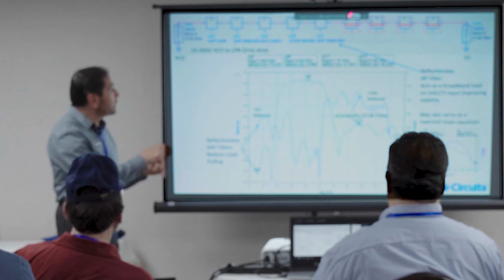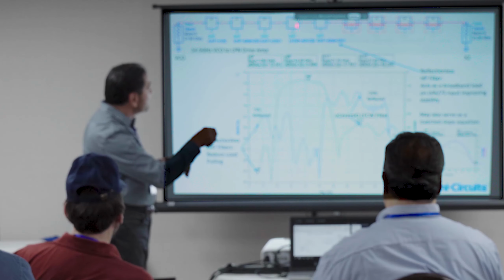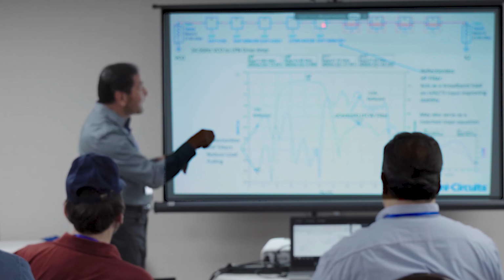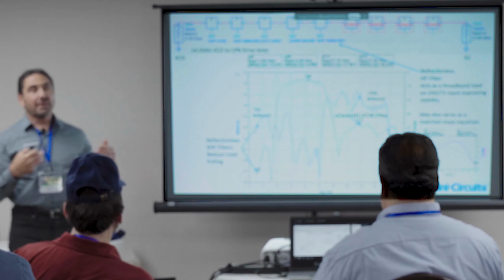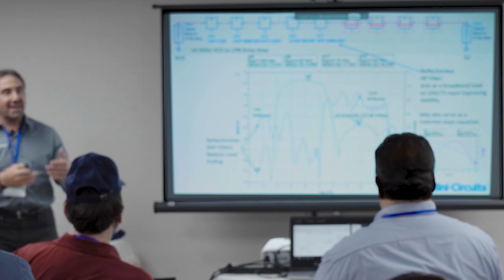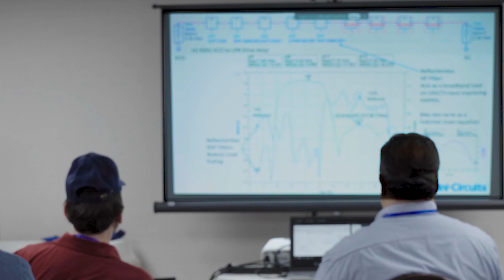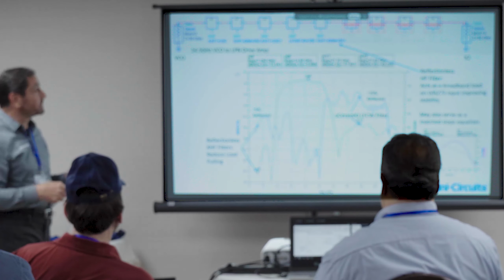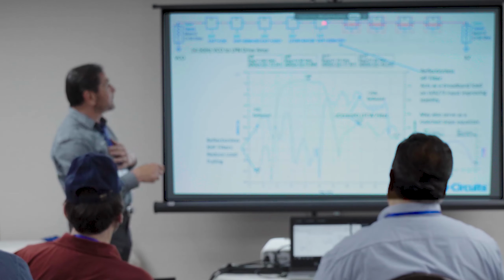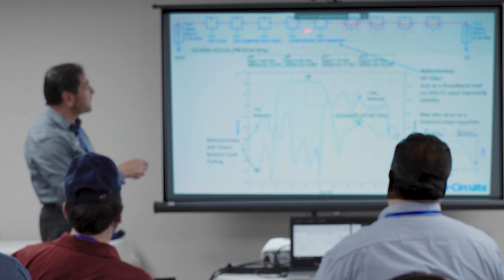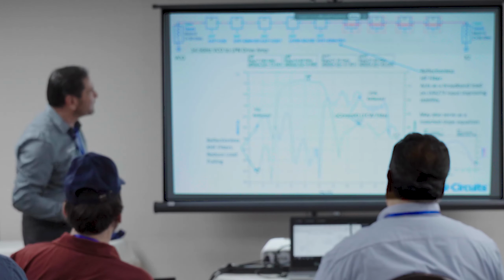When you're working in the reject band of this filter, this is in the pass band, so you get maybe a 2 dB round trip return loss. So that amplifier is not looking into 0 dB return loss. And believe me, a couple of dB helps. So that's a good technique that I like to use. I actually put one here so it provides some buffering from the reactive filter.